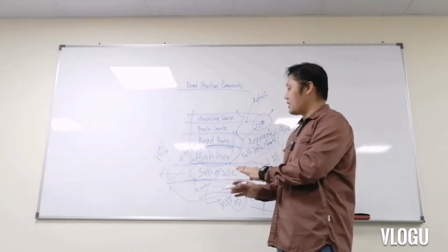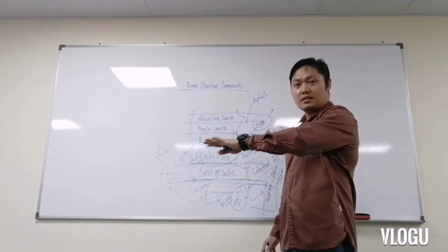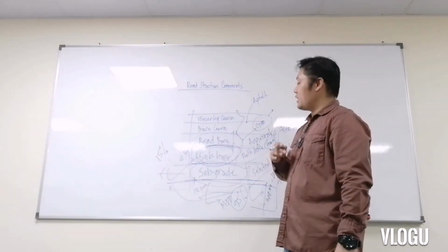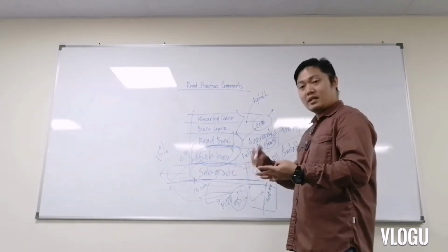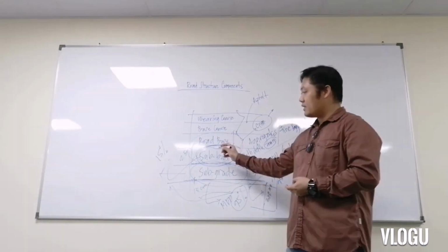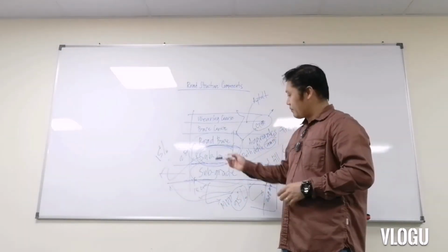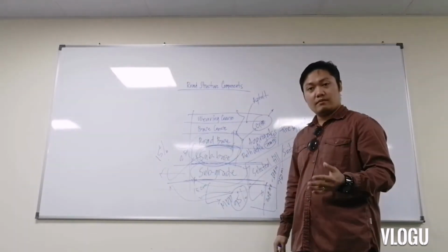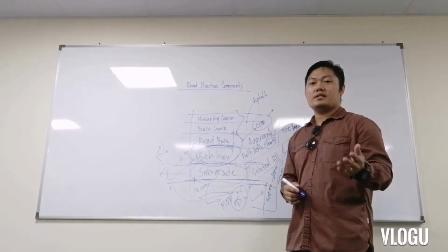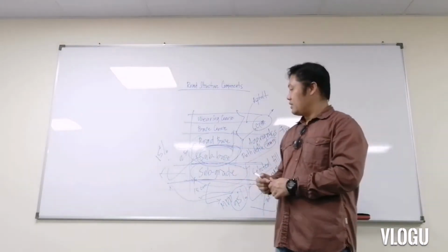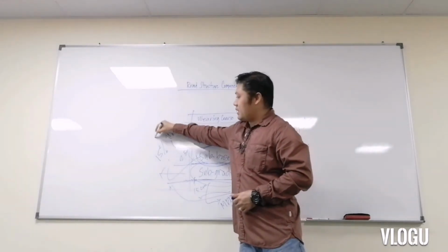And then, the same as the subbase, we are going to test it by means of field density testing. Then at the same time, we are going to conduct the CBR value, known as the California bearing ratio. We have to identify the CBR value. So once again, the same as the subbase, the percentage for the compaction of the road base, I mean, is 100%.